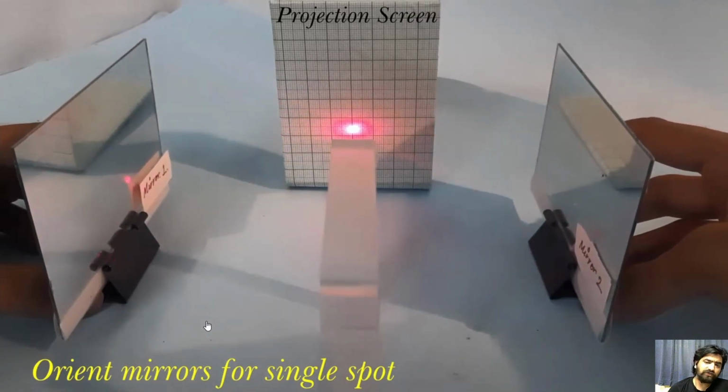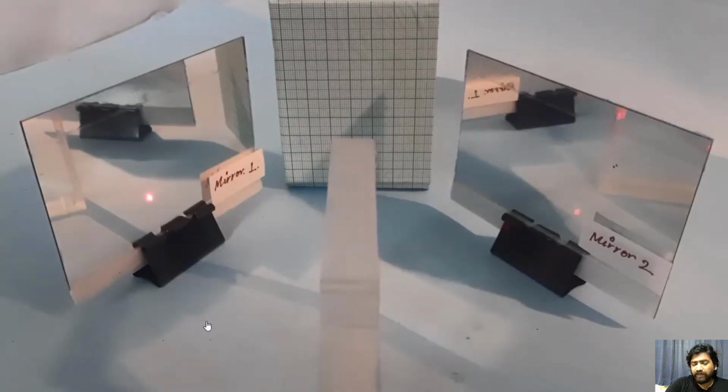Now you can see very clearly that we have enough space in between and we can feed anything towards the molten pool or towards the focal point from the empty space. So this is how they typically convert a laser beam into multiple beams and then further merge them towards a particular focal point in order to generate the omnidirectional unit, such that you feed the wire from the top vertically. So you can also try this experiment on your own.